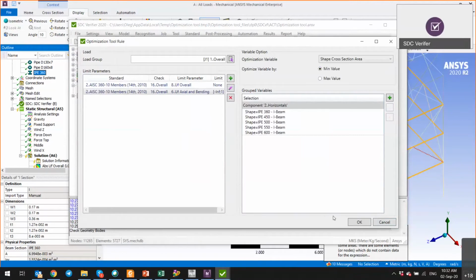Yeah, Michelle is writing that it seems only sections defined in the model were used. The parts of the model which I would like to verify were used, and the sections defined by me were used. So from this selection, you can run any. I just selected this to save time. I just selected 5 IPEs, but you can optimize based on the full library and run it for 400 shapes. It will take you maybe half an hour or so, but you're able to optimize on those. Okay.